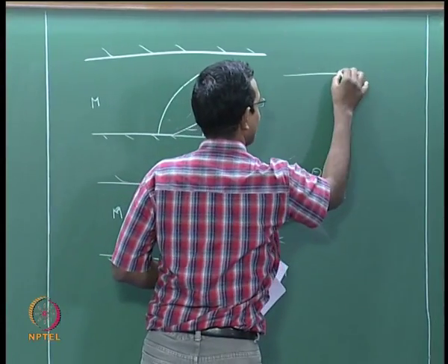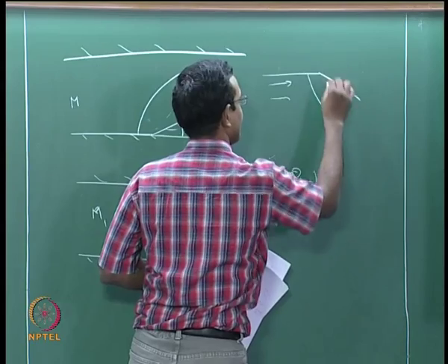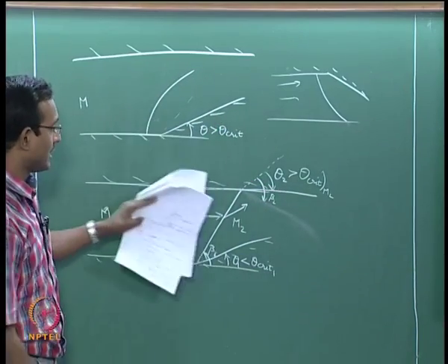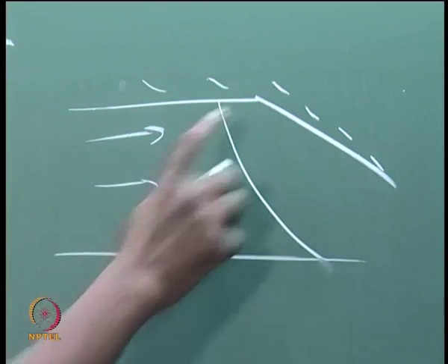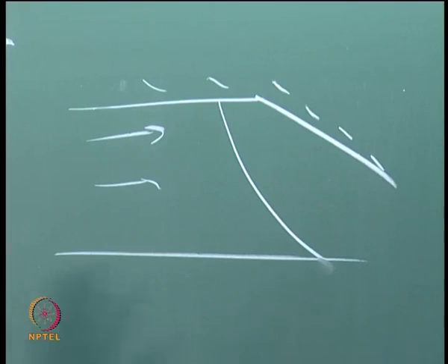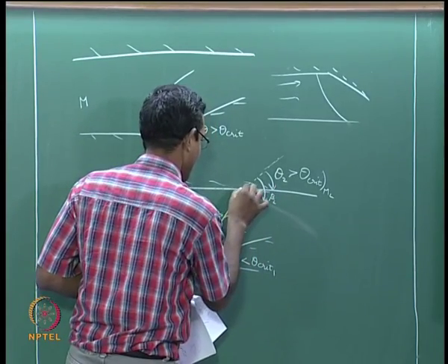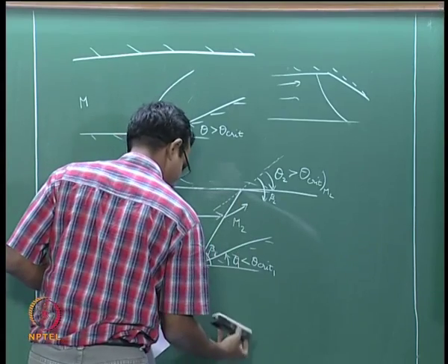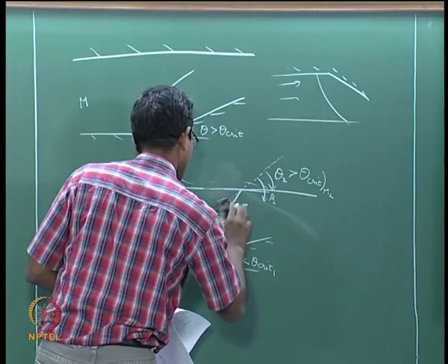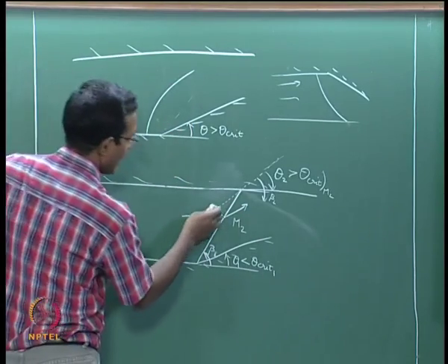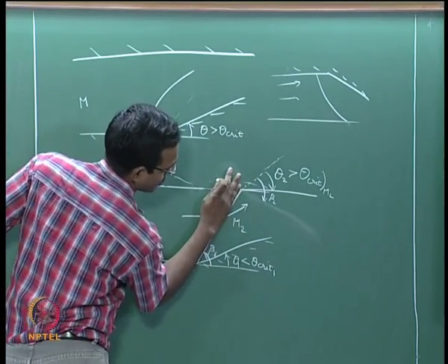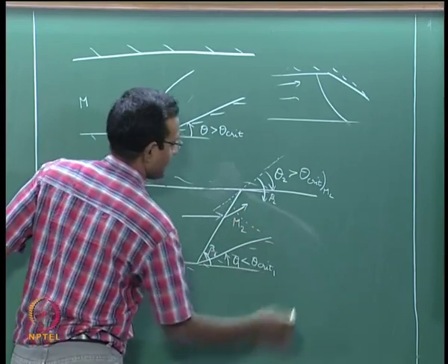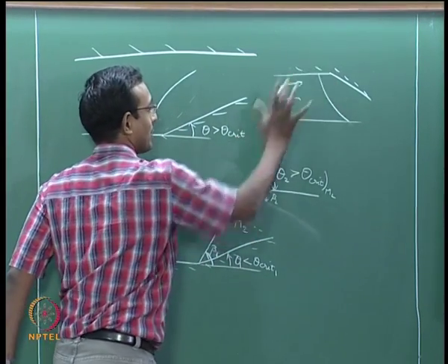I will draw that for easy imagination. It will look like this. Okay. This should be your picture finally. Okay. If that is the case, I have to tilt this slightly so that this wall becomes parallel to this dotted line. If I do that, then I will end up with a shock. I am having too many, this is causing more lines. Okay. Anyways, so I have this original dotted line. This is what is imaginary wall for the post shock flow field, which is going like this, and that angle is more than critical. So there should be a shock that is going like this. This is what should happen if I look at this picture with this slightly rotated.